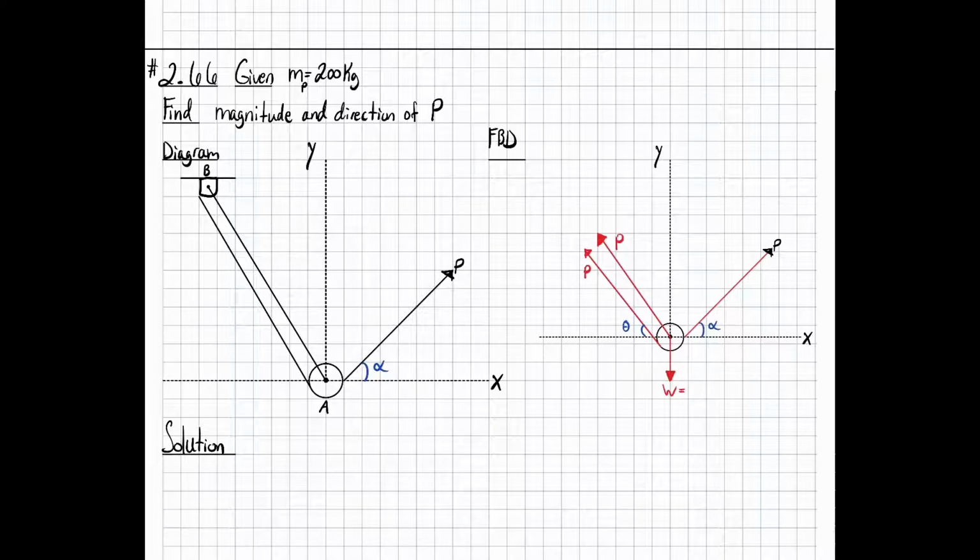So looking at the free body diagram, we have our main point A, which is the pulley. And knowing it's just a simple pulley, all it is doing is half the work of what force P would be. So this is just 2P. This is essentially just doubling the work. That's how you have mechanical advantage.